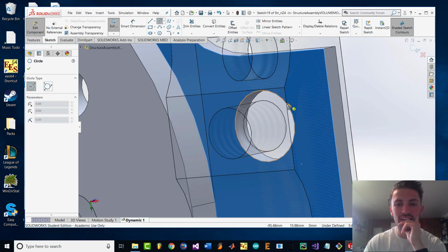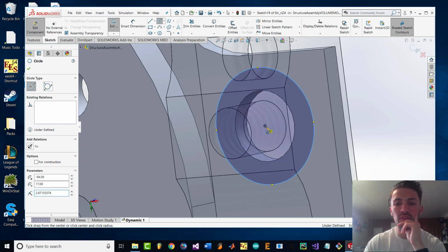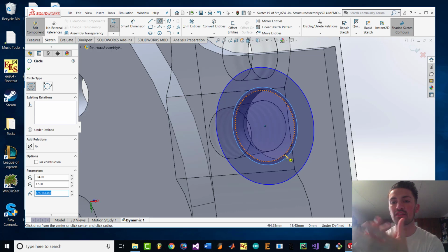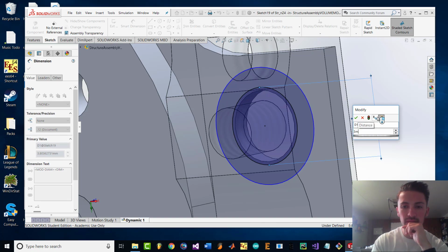That's an important detail. Then we're going to create a circle, if I can get it to pop up, there we go. We're going to create an area that models the contact area of the bolt. So if we're using a 3mm bolt, the socket head itself is about 5.5 millimeters wide, and then shrinks down to the threaded part. The difference between the 3 millimeters and the 5.5 millimeters is the surface area that's actually pushing the force down to connect the 2 parts. So we're going to model that here.